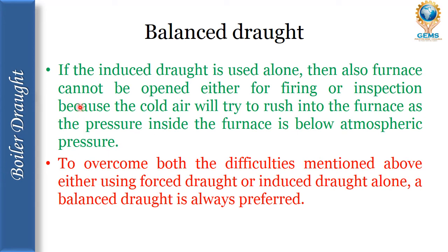Next, if the induced draft is used alone, then also the furnace cannot be opened either for firing or inspection, because the cold air will try to rush into the furnace as the pressure inside the furnace is below atmospheric pressure.